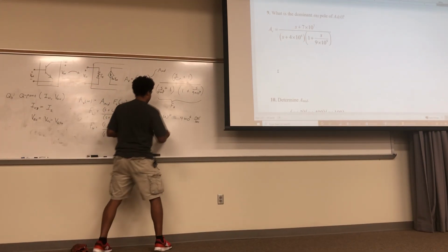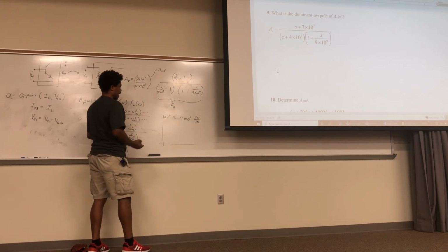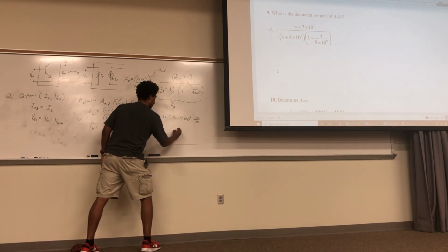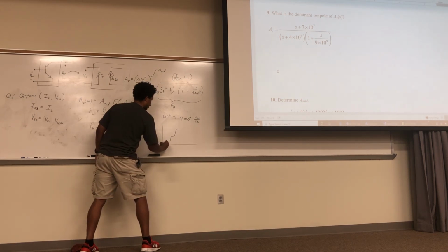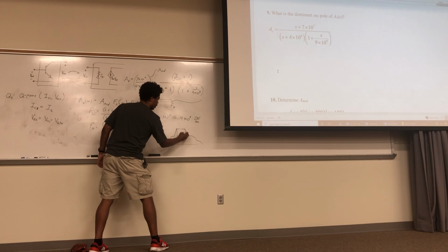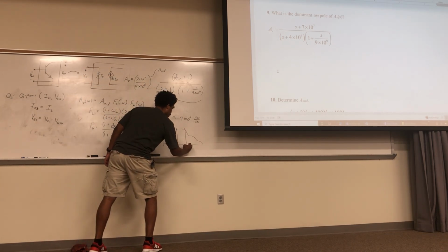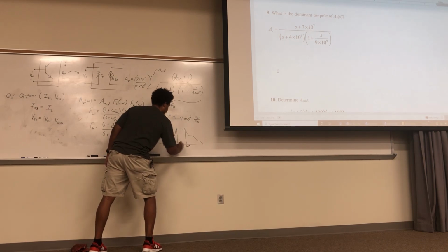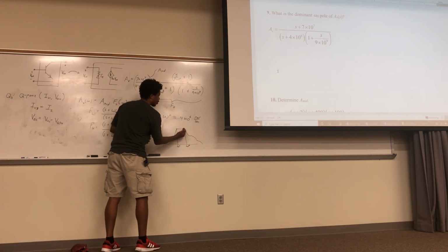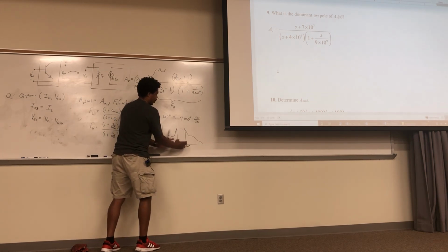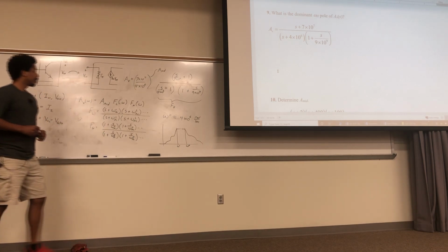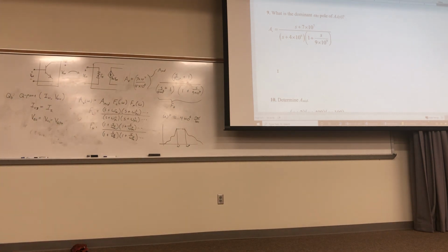Yeah, let's give a basic example of something that would be some A mid, and then you'd have some other things that fall off. So you would have, this right here, may do something else. Same over here. So these are dominant poles right here that you're really concerned about. Okay, so this will be your dominant pole for omega H. This will be your dominant pole for omega L. Because typically, you're concerned about this region, and that's the region where you're saying, hey, here's the bandwidth, right? Even though you have these other omega H's out there, that's your dominant.